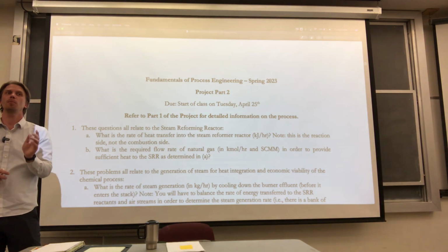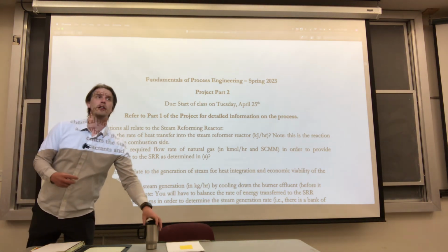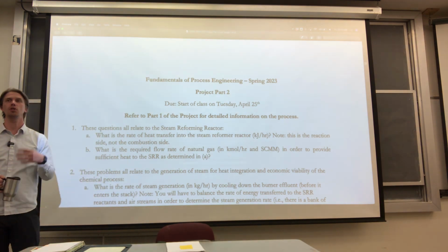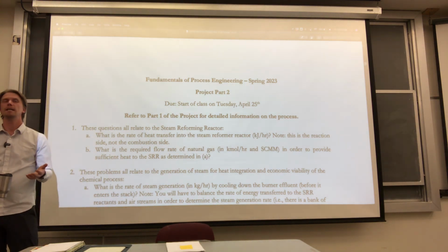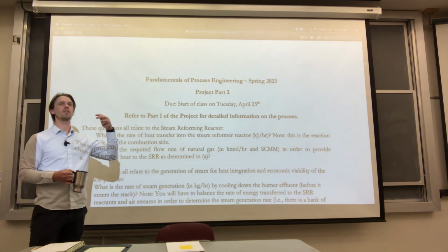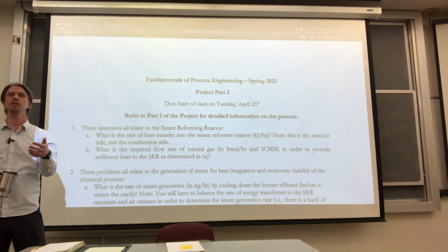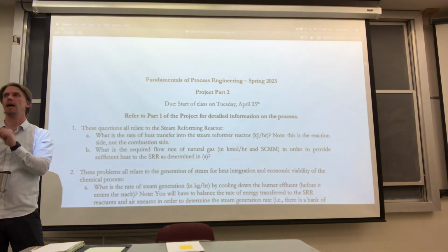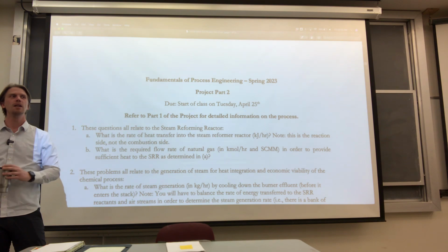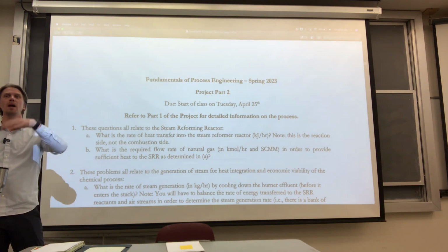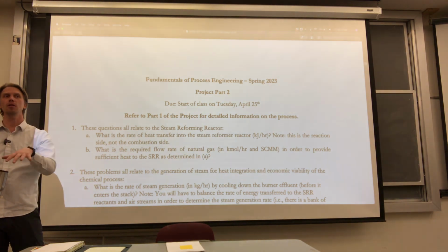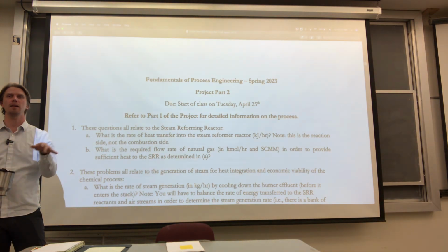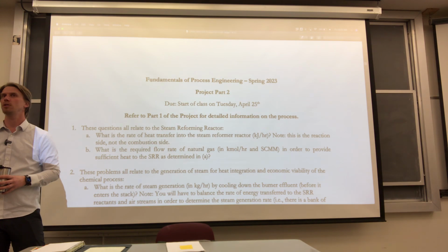So maybe something to brush up on is that when you have a non-reacting system, you get to choose a convenient reference state. The only reason the reference state is fixed for a reacting system is because we don't have data except for the energy released or consumed in a reaction at 25 degrees C. So go back, and if you got number 3 wrong, please take a look at reference states again and brush up on how to calculate heats of vaporization at arbitrary positions.